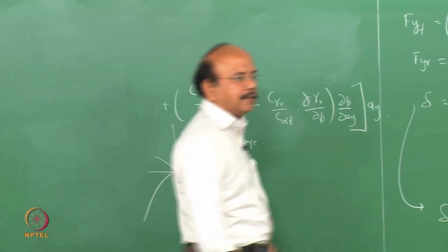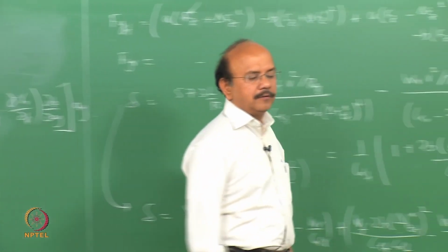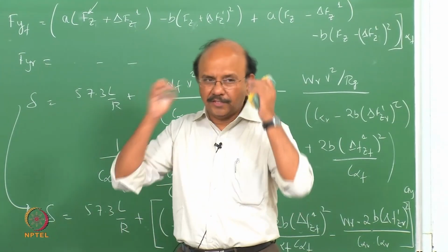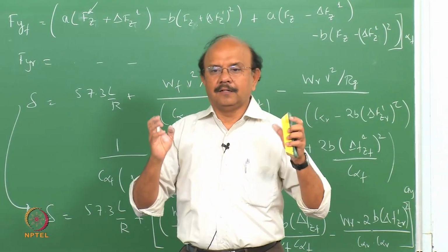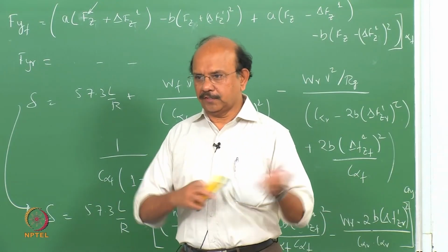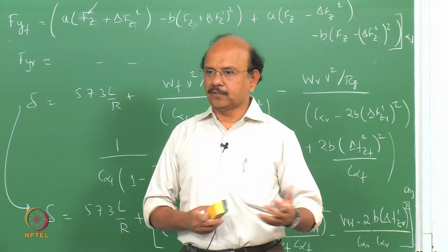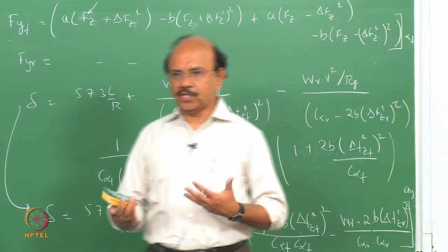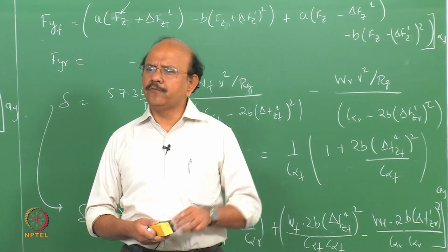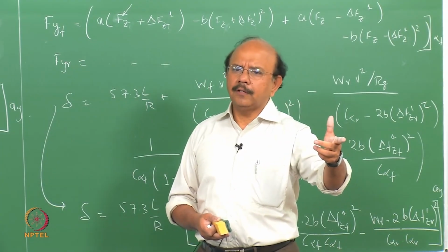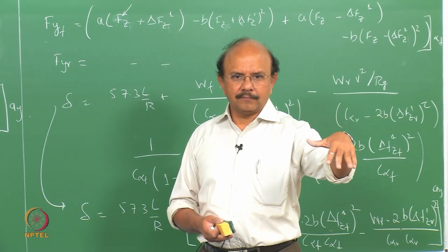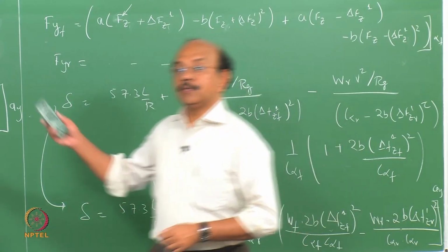It's so important that there are tests to do this. Imagine that, obviously there's going to be a change, we'll see that in the next class what the change is. Imagine that you're taking a turn and you're applying brakes. So there's a redistribution of forces, because of which there's a change in alphas. And when there are changes in alpha, obviously you will feel a different steering input is required. Okay? So that's the next effect.